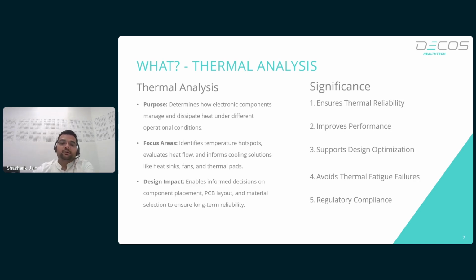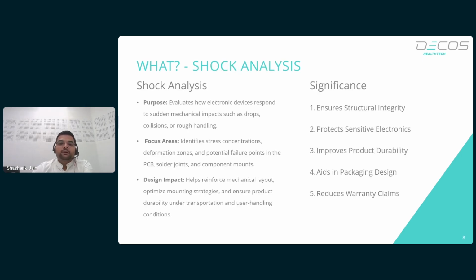And lastly, it also helps you to regulate compliance. It assists in meeting thermal safety standards which are defined under different standards like IPC, JEDEC standard, etc., which are also critical for certifications and different market approvals before you enter into a particular market. Now here I'll be discussing what is shock analysis. The purpose of shock analysis is to evaluate the response of an electronic device to mechanical shock and impact, which a device may experience during operations or during transportation.